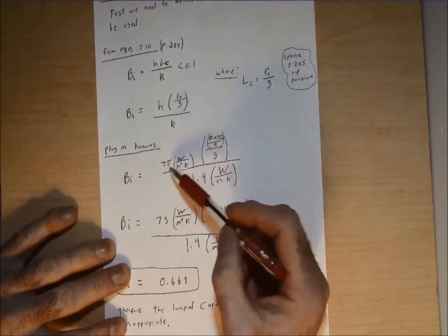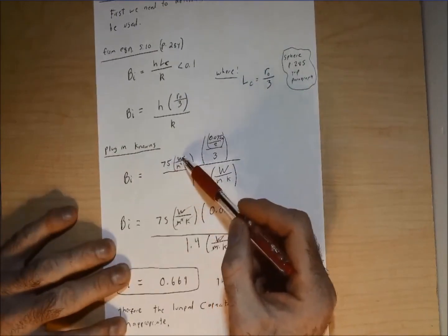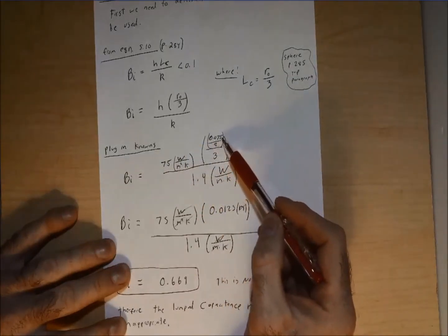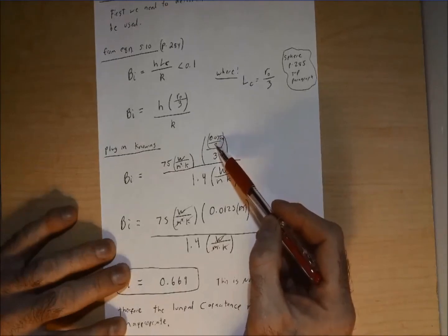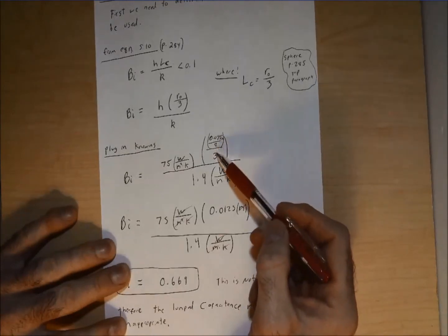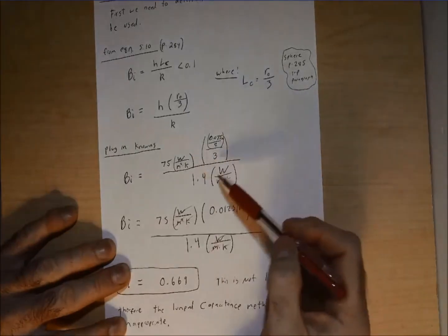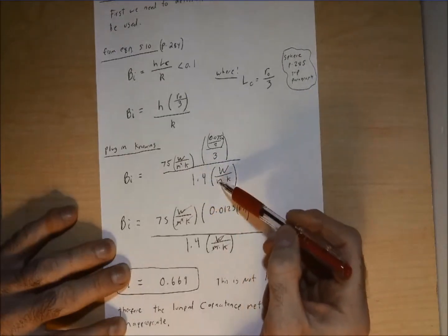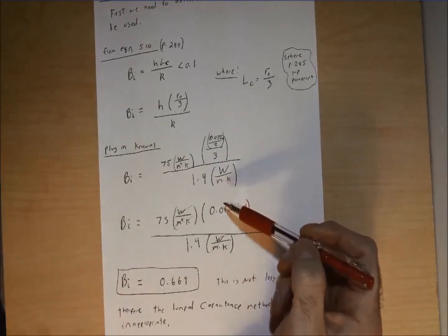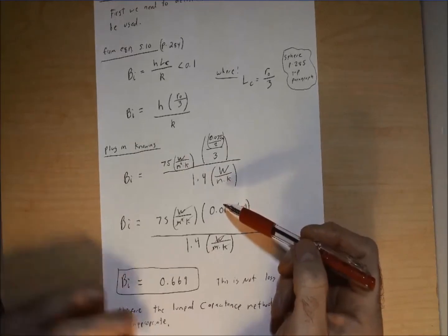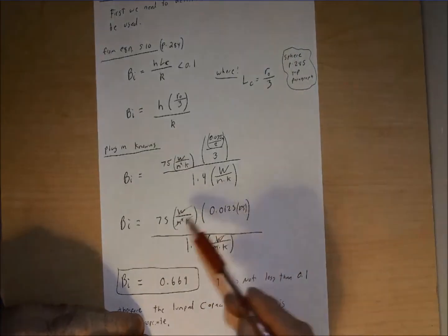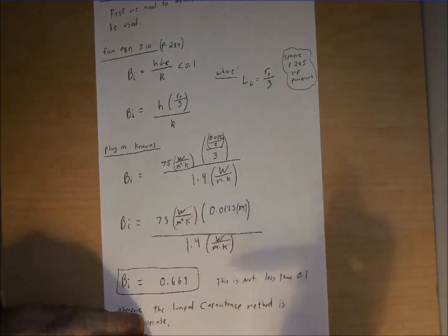So as we do that, we see our H value is given to us as 75 watts per meter squared times Kelvin. We have our R naught of 0.075 meters divided by this 2 from diameter down to radius, and then this is divided by 3 from the equation above. And then the bottom part of this, our K value, which is given to us in the problem statement, is 1.4 watts per meters times Kelvin. So now we've plugged everything in, and what I want to do is some unit analysis. Double check, see what cancels out, make sure things are in the right units at the end. Watts, watts, meters, the squared there, meters down there, K, all our units cancel out. We're left unitless, which is exactly what we should expect.